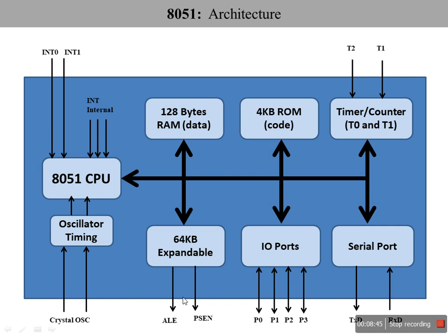The maximum limit given by 8051 is that you can interface 64 kilobytes of external memory to 8051. This is facilitated with ALE, address latch enable, and PSEN, program store enable. So using these pins we will be able to extend the memory.